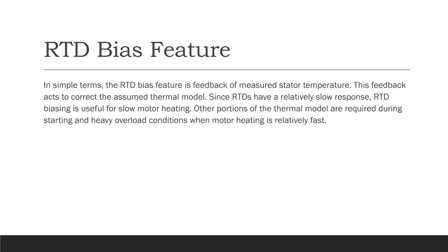This slide is right out of the manual, and I'm just going to let you guys read this, and I'm going to talk about it. And this tells us, and we need to emphasize, that a motor protection strategy involving RTDs only is not a viable strategy.